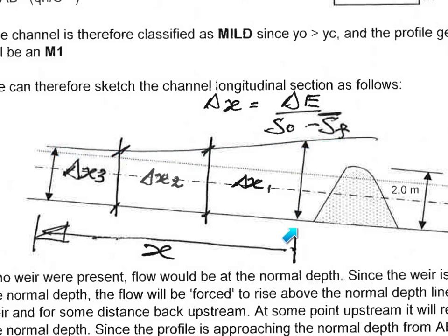What we do is divide it into sections. How many sections? Well, we need to know a starting depth and a finishing depth or section. And then in between, we should aim to go for 3. So that would give us 5 sections, 4 increments. But if we're pushed for time, we could go for a start, a finish, and 2 internal sections. That would give us 4 increments, but 5 is the best compromise to aim for.